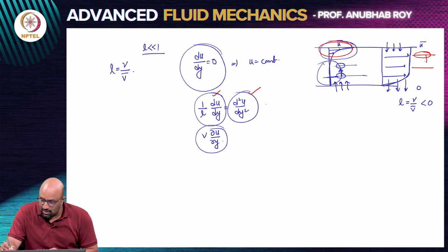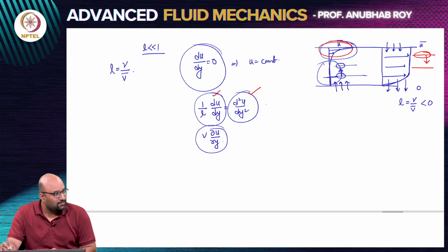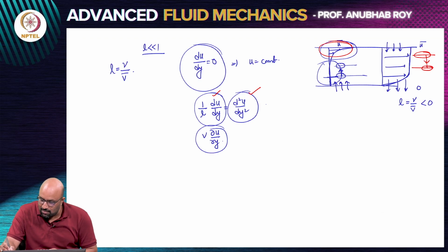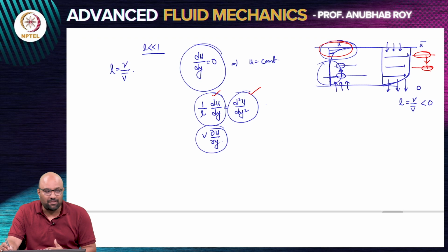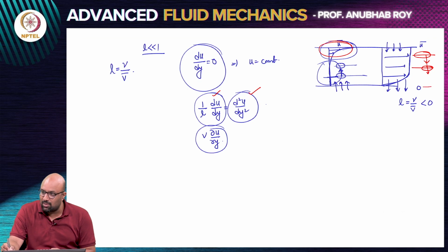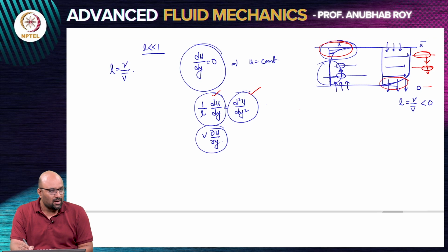Now the vertical velocity is actually aiding it. It is acting in favor of transporting the fast moving fluid. So it is continuously making the bottom layers move equally fast, if not as fast as possible. So there is this continuous transport till it comes close to the bottom plate, where viscous diffusion is going to compete with advection. So this is a competition of advection and viscous diffusion in your momentum transport.